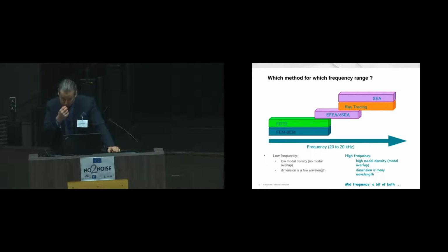For which frequency range? You have some approaches that are more well suited to low frequency and some more suited to high frequency. Finite difference, finite element, BEM method, all of them are very accurate, directly solve the PDE equation, but they tend to be very costly when you increase frequency for reasons I will show later. Then you have high frequency approximation like SEA or ray tracing that do not work at low frequency.